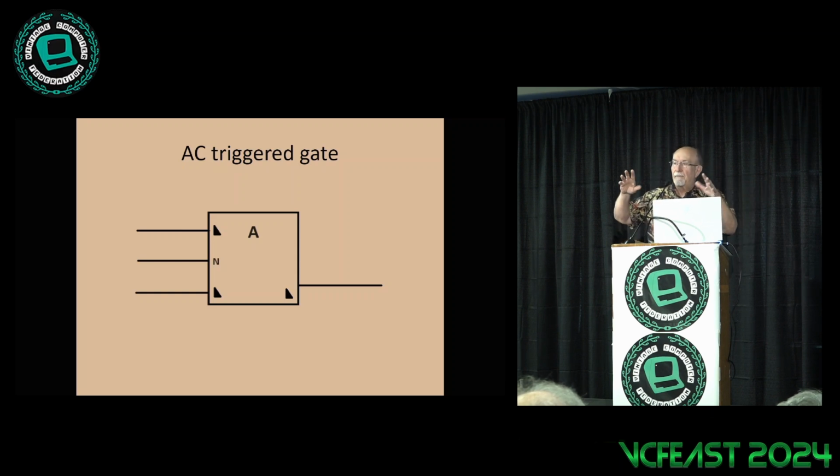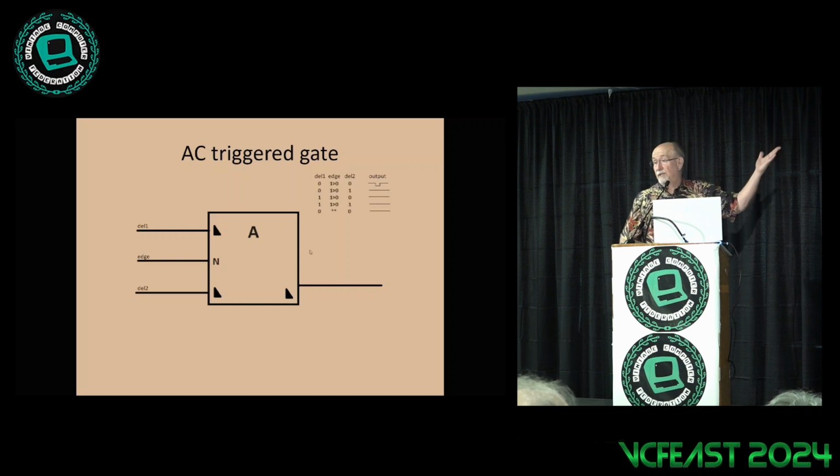So a lot of things are happening kind of asynchronously, which is good, but it's also bad if you're trying to catch this on a logic analyzer and you're using the clock as the sampling point. You might miss something that happened just a fraction after the clock. So the truth table is just this: if all the arming inputs are on, then you get a blip.